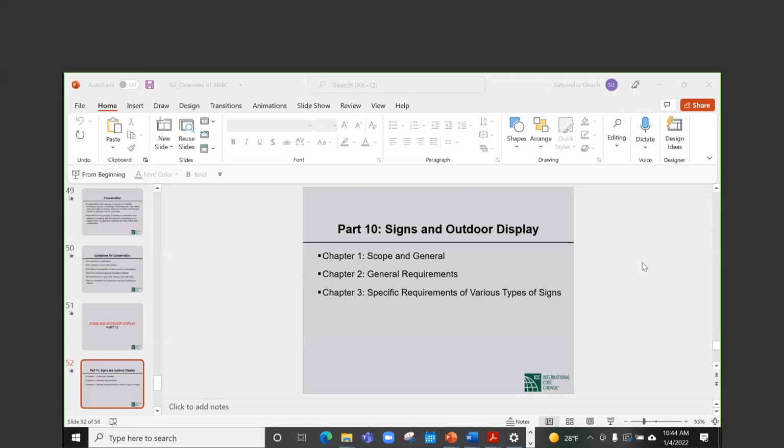The answer to the first question is yes. Over-reinforced beams are not allowed to be built by ACI 318 or BNBC 2020. So if some beams are over-reinforced, those beams are out of compliance, and it cannot be that the beams of a frame are out of compliance and the frame is in compliance. So you have to say the structure itself is out of compliance. Is it unsafe? In my judgment, it is unsafe.